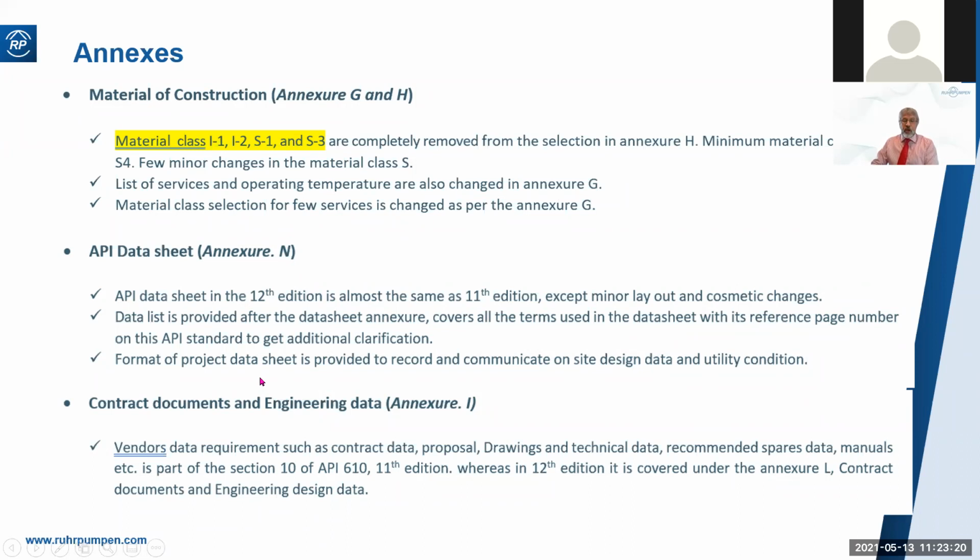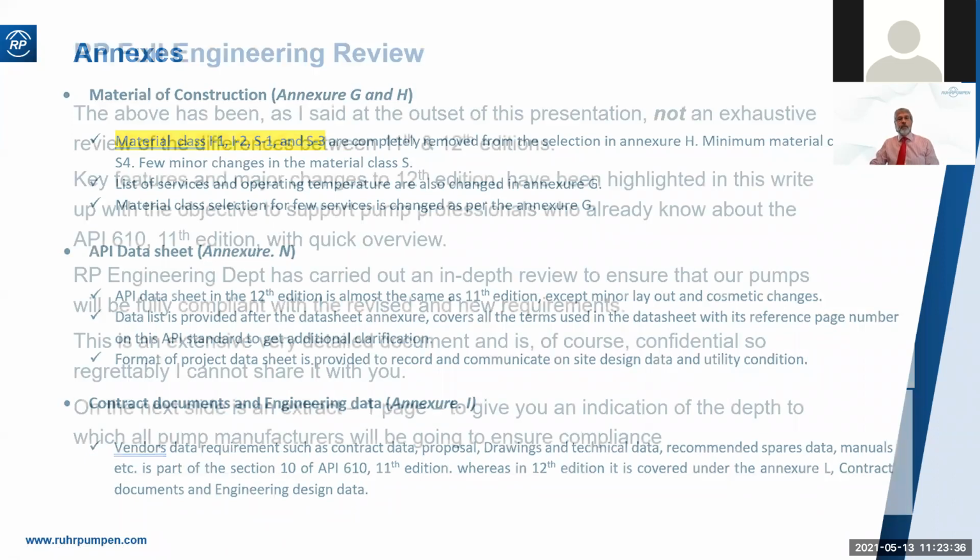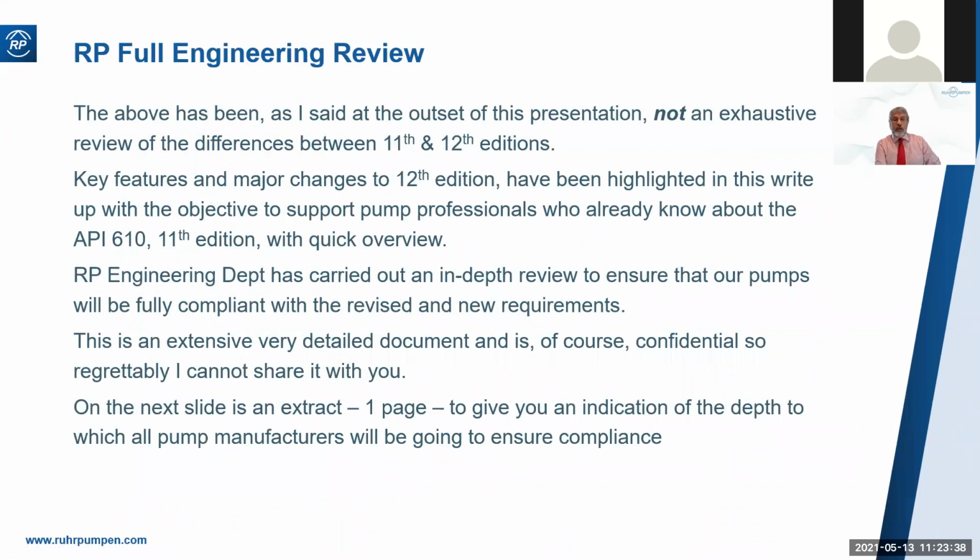Data sheets are essentially the same as they were for 11th edition, but we can expect to see API-610 data sheets added for the more difficult pumping applications. Now, as I said at the beginning, this is an overview rather than an in-depth analysis, just the key points that are likely to impact you as a pump specifier.